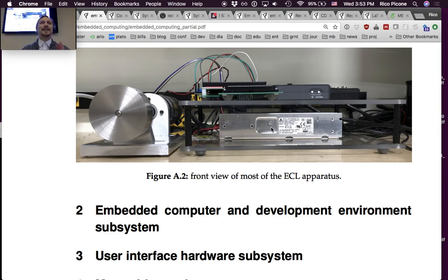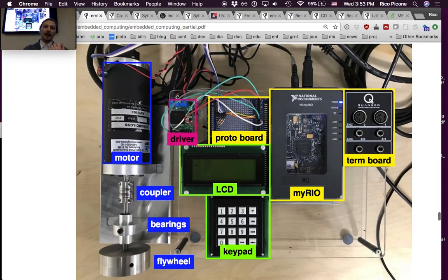So you have the DC power supply. It can supply a lot of power, right? And then you've got your myRIO, which can't supply a lot of power, but has this variable pulsing capacity. What the driver does is it brings those two together. You plug in the DC power supply with all of its power, and you plug in the myRIO with its pulsing, and it essentially gates the high power with your low power signal.